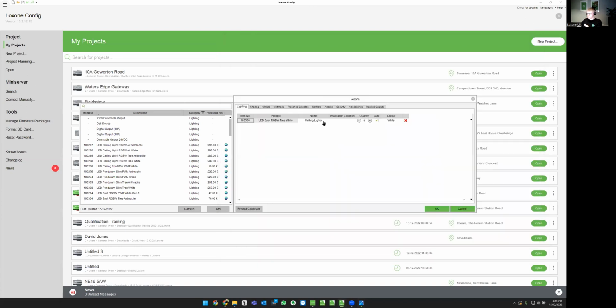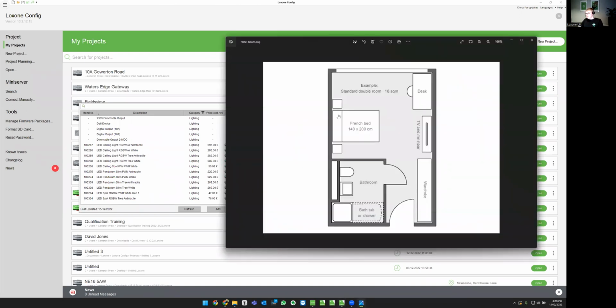So what we'll do is we'll get straight into it. You can see there 4 spots is calculated about right, and we'll just call these spots. Now, in terms of additional lighting in this room, I would just go for some LED strip around perhaps the headboard. Now, with LED strip, it's more than bright enough for focus light for things like reading and also watching TV with the main lights in the room off. So I think that would be more than sufficient.